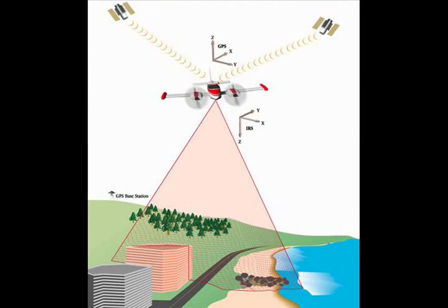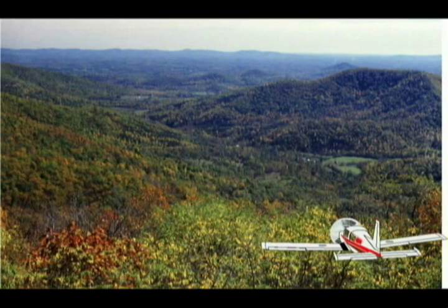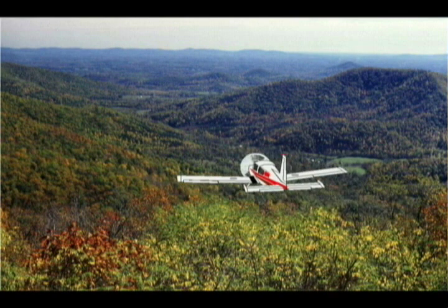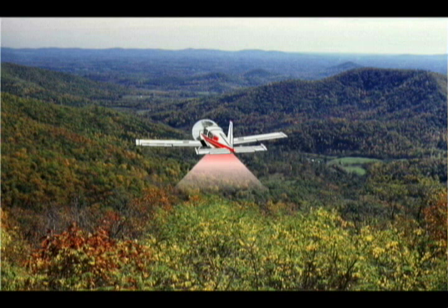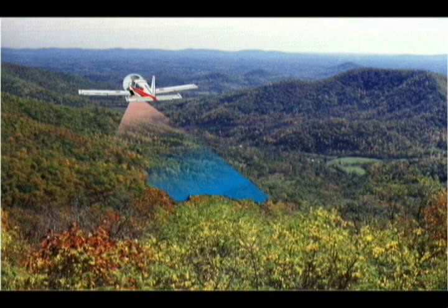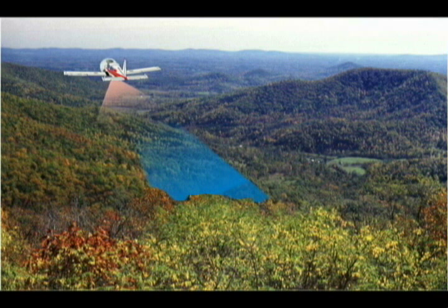This records all the data from all the systems and sensors and converts it into millions of XYZ coordinate points. All these components together, the laser, the IMU, the GPS, and the computer, are the basic units of the Lidar system. From the Lidar platform, the laser fires thousands of pulses to the ground every second. The scanning mirror detects these pulses in a swath following the flight path. These are reflected back to the onboard detector where distance to target is measured.